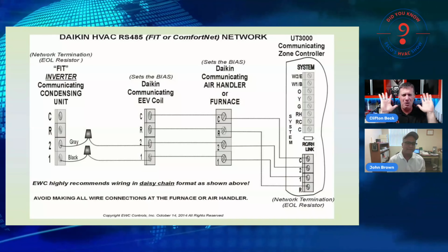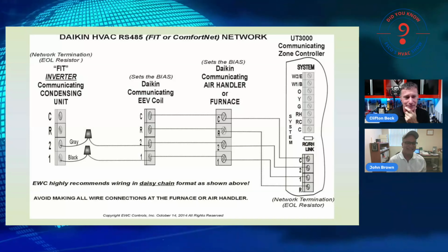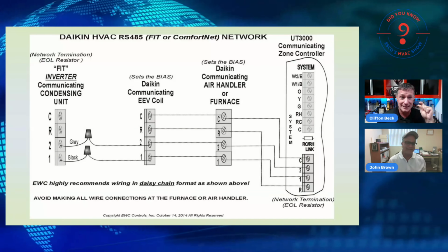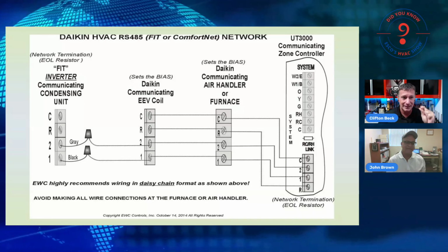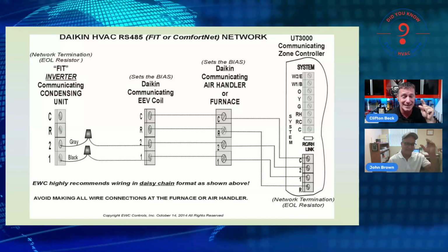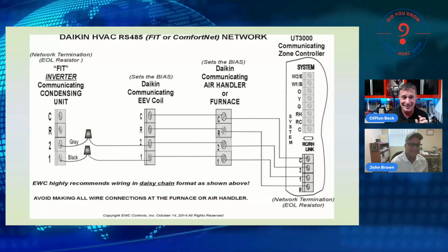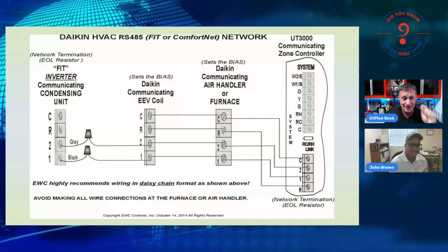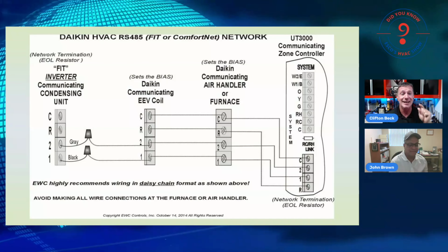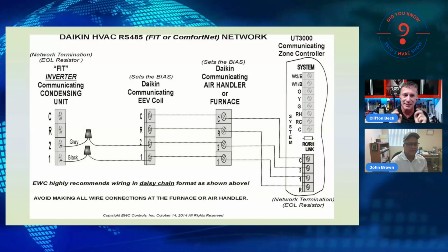And technicians go, oh my gosh, all that technology. And I go, what are you doing when you put your digital gauges on a piece of equipment? You are using, by the way, a 5-volt DC pressure transducer to calculate the pressure of your suction so that your gauges have a number to work with. And we're also using a 5-volt DC temperature reading to measure the suction line. And now we have two numbers that we can calculate superheat with.